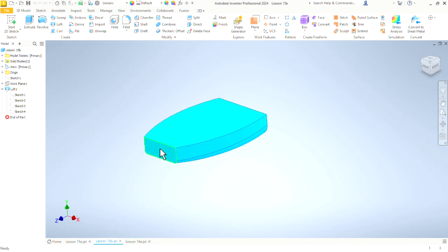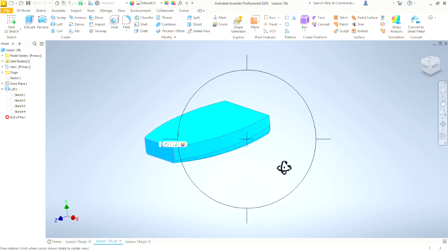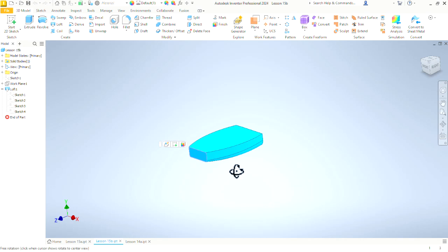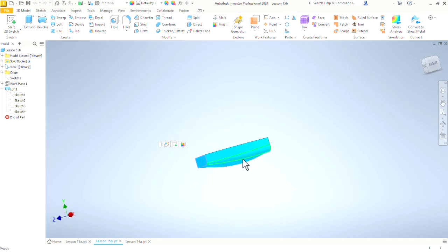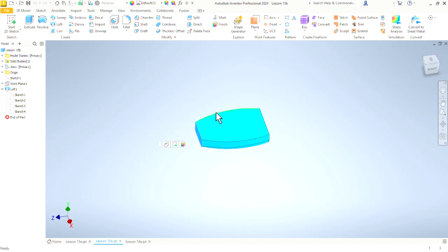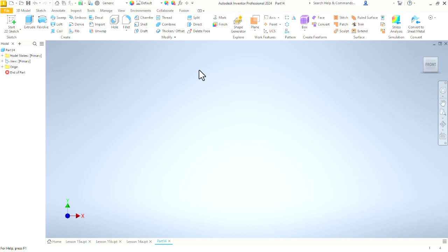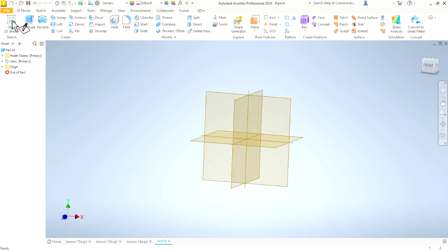Here's another example where we have again a profile on one end, profile on the other end, but they are joined not by a direct loft, but we have a bulge out to the side on each side here, and then a little bit of a belly underneath. Maybe this is sort of the hull of a boat, and we create some curvature to it instead of going just directly from one sketch to the other. So let's dive in, start creating these parts, or at least something that looks like them, and see how we add that control to the Loft.